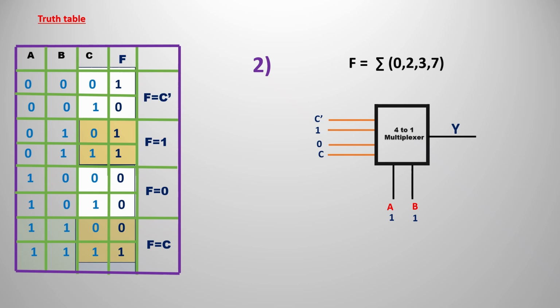So we are going to have another box. We are going to implement this truth table logic with the help of only the 4x1 multiplexer. In the 4x1 multiplexer, we are going to have two select lines. The two select lines are A and B, because we have three variables. Out of three, we send two variables there, and the third variable should be sent as input lines. For that, we compare F and C and write them as inputs. I hope you know this.